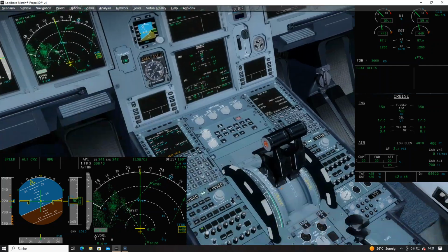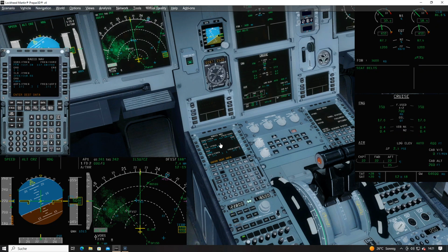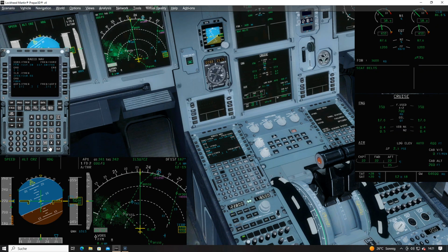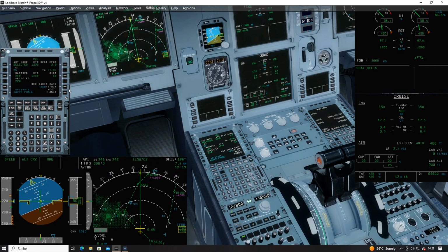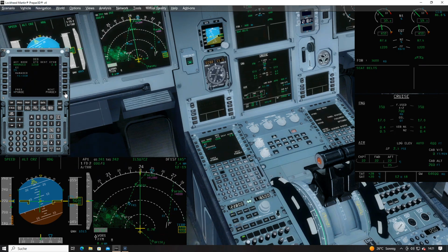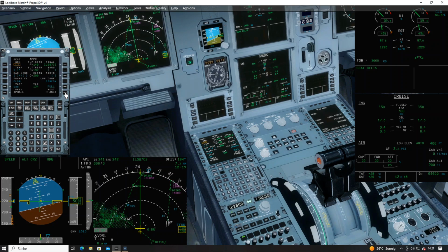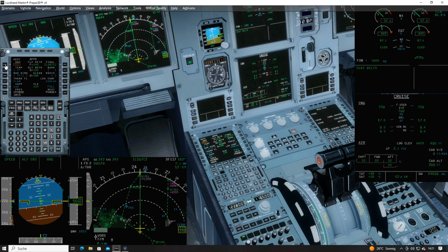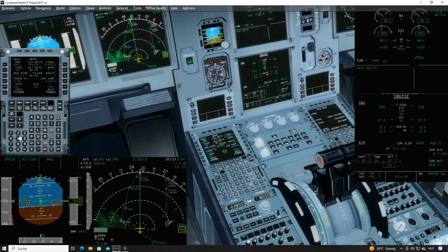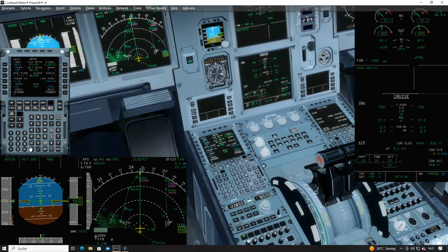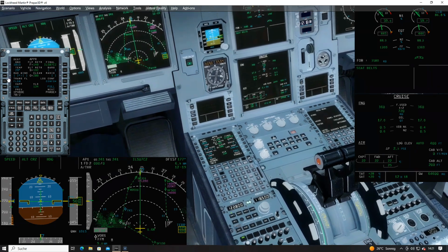For approach, the FMS wants to know some things for calculation purposes and for destination data we are asked. So we go to the performance page, go to cruise phase, next phase is descent, next phase is approach. The QNH, the local air pressure, is inserted, the present temperature, and the wind, which is almost 0, I think. So we'll just make some number.